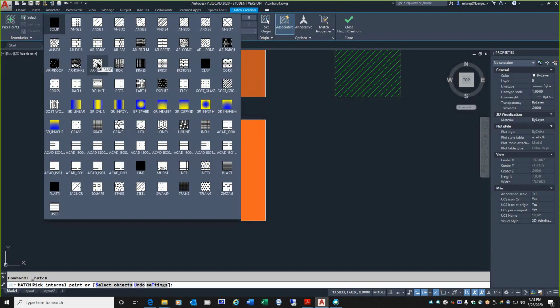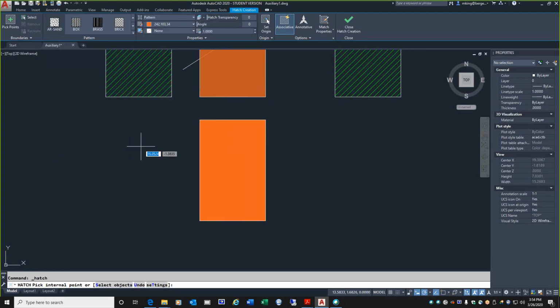So I'm going to click on the pattern. Before I even put my mouse in there, because I probably won't see anything, I'm going to click and highlight the scale of 1, and let's type in 0.25, okay, a quarter of the scale. We may have to go lower, right? Enter. Now when I put my mouse in here and I move around, not seeing much, so let's take a chance. I'm going to highlight this, and let's type in 0.05. Right, that's going down pretty low. 0.05. And then I bring my mouse in here and hold still.